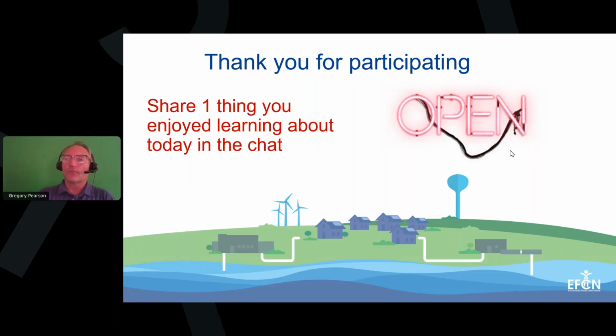Next, someone was wondering, what does the coating of the filter media with coagulant do? What benefits are offered by this? The coagulant coating the media allows the media to adsorb. So you have a particle of sand and it's coated with alum, for example. That particle is now positively charged, and a negative turbidity particle comes along, and it's going to stick to it because of its electrical charge.